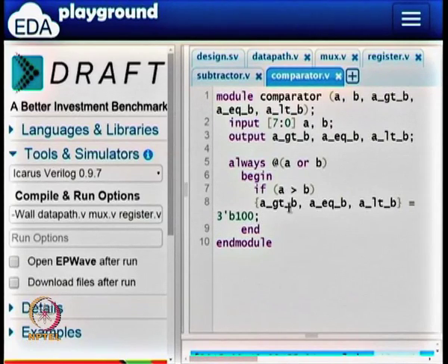On the left side we have grouped 3 bits together by putting what is called the set bracket. On the right side I have what is called a bit vector. The bit vector is a 3-bit vector. So this B says it is a bit and this 3 says it is a vector, and the values that are supposed to be in the vector are 1 0 0. So that is the first line.